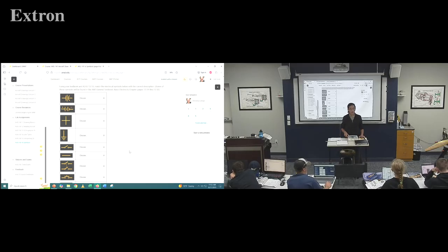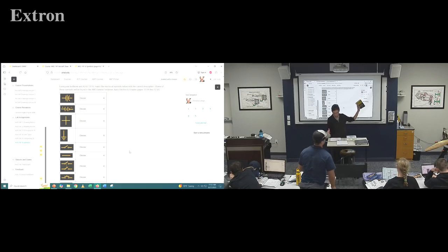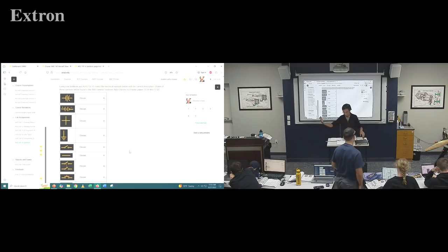But for working on aircraft, like how to do something for sheet metal, you have to use AC 43.13, not your textbook. The page numbers again? In the little handbook, it starts kind of on page 80 and following.